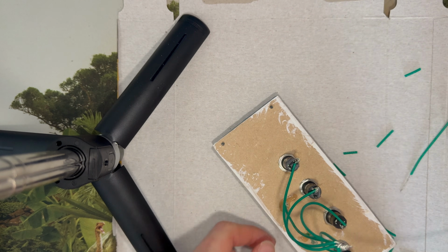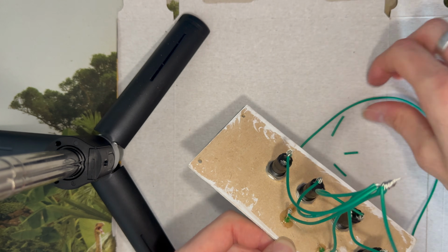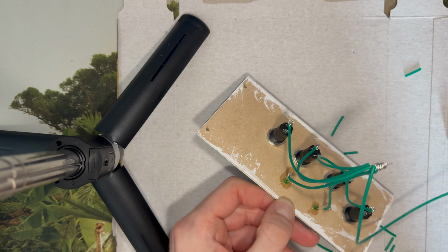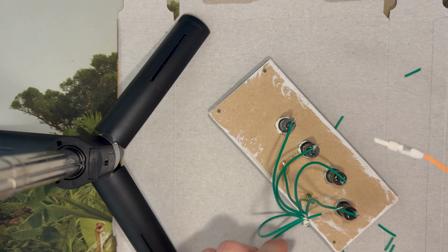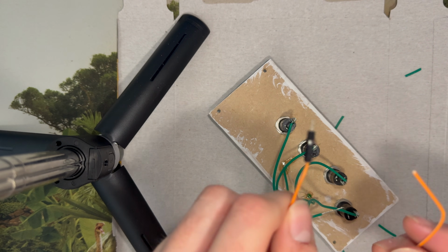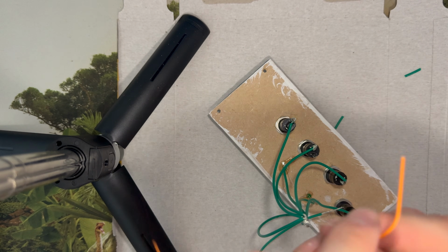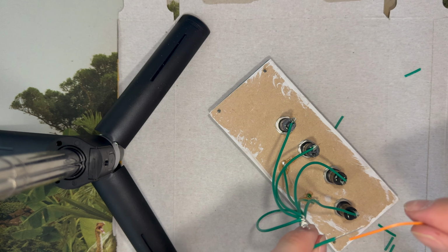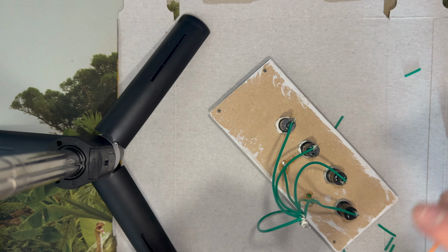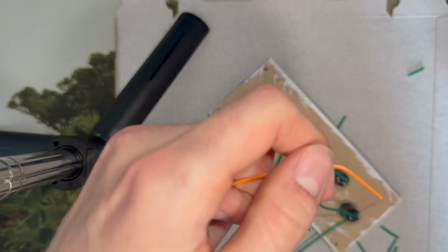Now all the components, including the LEDs, as you can see, they're all wired onto the common ground with a longer wire coming off. On the end of the longer wire I've trimmed it, and I'm going to use this wire, which is a connector jumper cable, which will go into the board. So I just need to strip this end, connect it to there, solder it, and then this just plugs into the board, into the ground pin. So we're going to do that now.